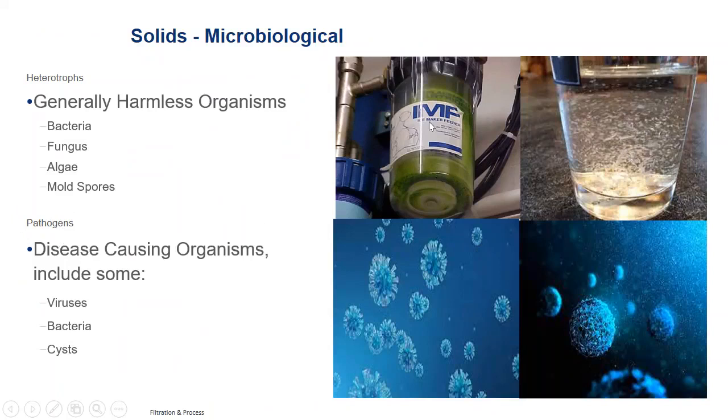And algae. This is a great illustration that our water systems aren't sterile. This is a 5-micron cartridge system from our Everpure group, and this is a phosphate feed bowl on the back end. It's clear, but algae made it through these filtration devices into this unit where it got enough light to grow. So algae can be a factor. We sell sleeves to cover these to keep the light out. We're not going to remove the algae because it's harmless, right? And there's typically not enough of it to impact anything from a taste perspective. But in a commercial application, that may be entirely unacceptable.